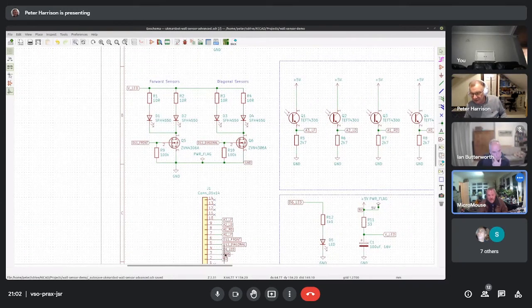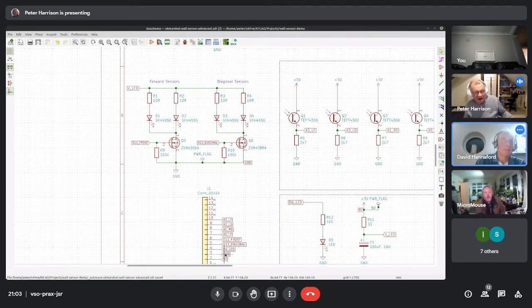So it's saying that that ground symbol in Eagle would constitute a label called ground, but in this, doesn't. No, it's an annotation, right? It's an annotation which also gives a name to a net where that's appropriate, I believe. I haven't looked into the details, but if I took away that label and this label, assuming that my mouse is catching up on the screen, if I took away those two labels, nothing would change. Right, and you could put a ground symbol on the connector at the bottom, and it would then connect. Yeah, it would be fine.